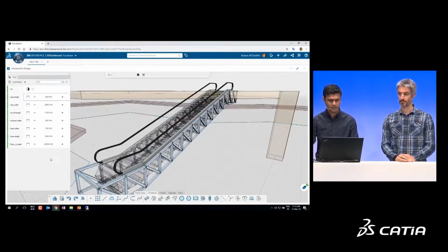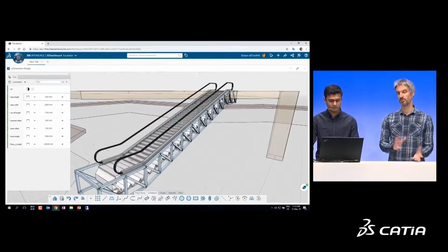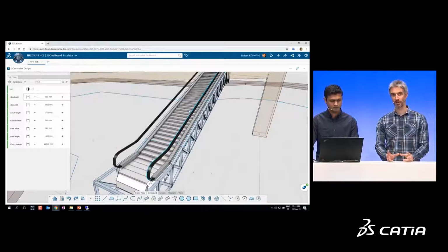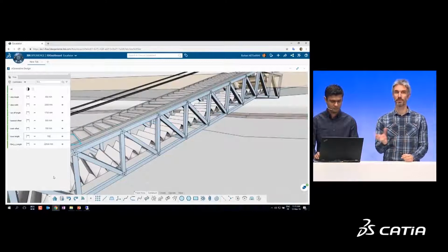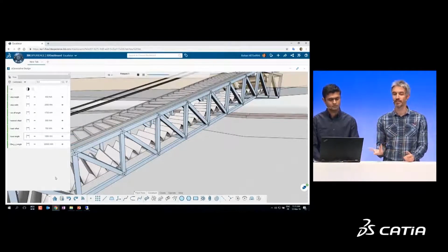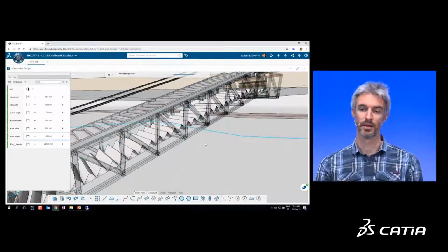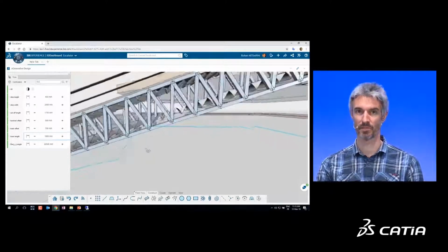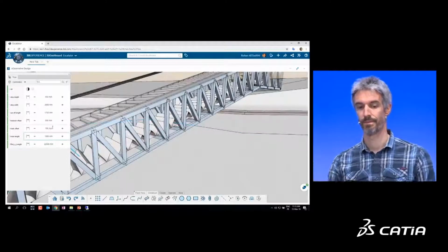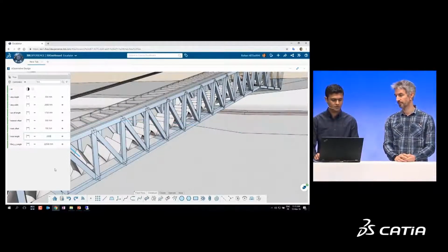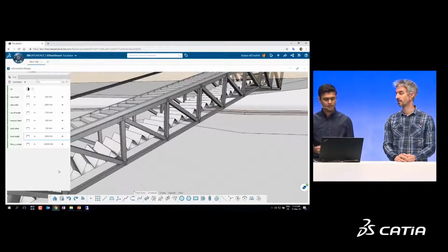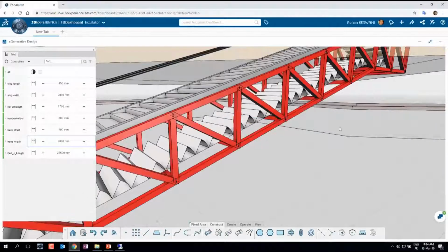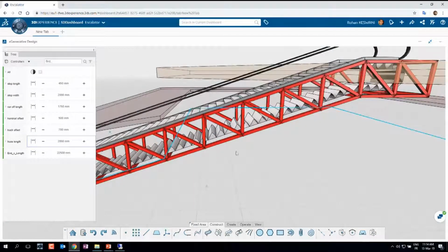So now I'm going to make some changes to the parameters here. So for example, I'm going to change the step length parameter. Okay, so we have created here some kind of product configurator. In fact, you have the main parameters of your stair, and you can just edit them, and you have a live update. The geometry is automatically and live updated and recreated. So you can very easily edit some parameters and see your result in real time. Absolutely. And also what's interesting is we've included some design checks all within the same model. So in the form of some color coding and things like that. What we are able to see now, for example, I introduced a value for the length between the truss members here.